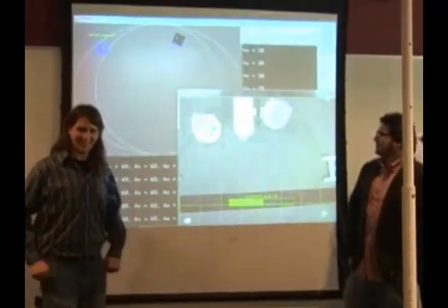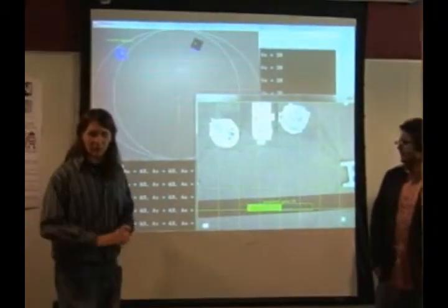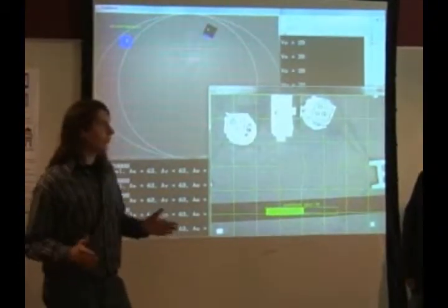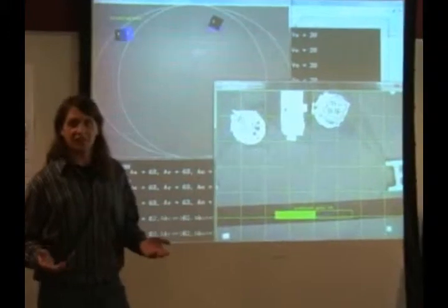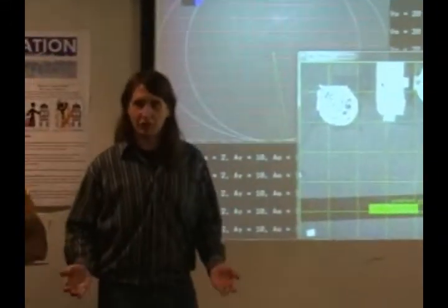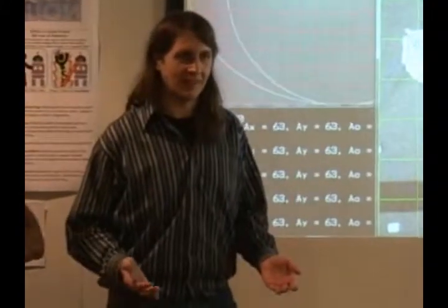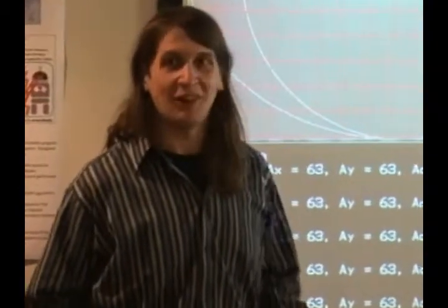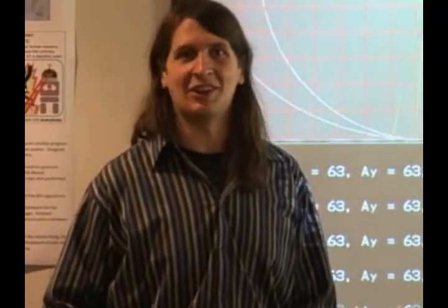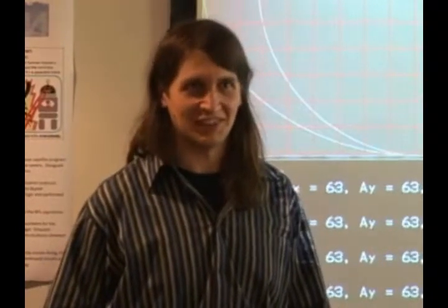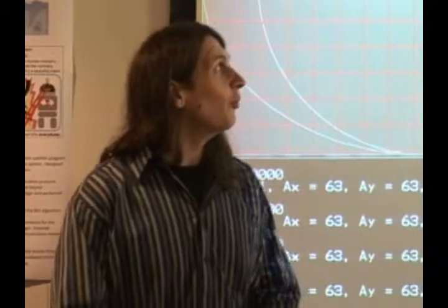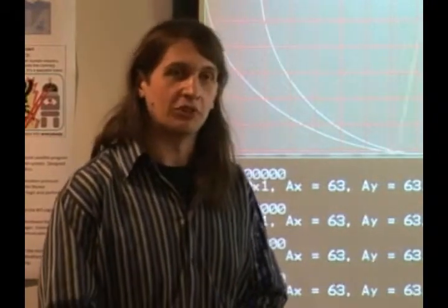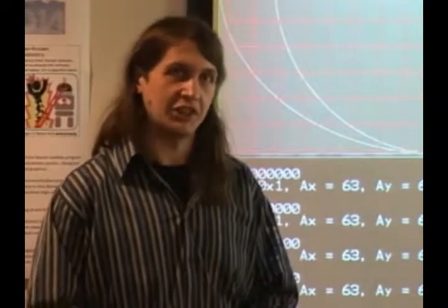Yes, so Skynet is the program we're using to do all the localization. That was one of the biggest problems we had going into this project: how do the robots know where they are in the world? It's a pretty big problem, particularly in this class, where people who propose to do localization as part of their project usually wind up making their entire project solving localization. So we used some libraries and programs that are open source. One we're using is called Reactivision.